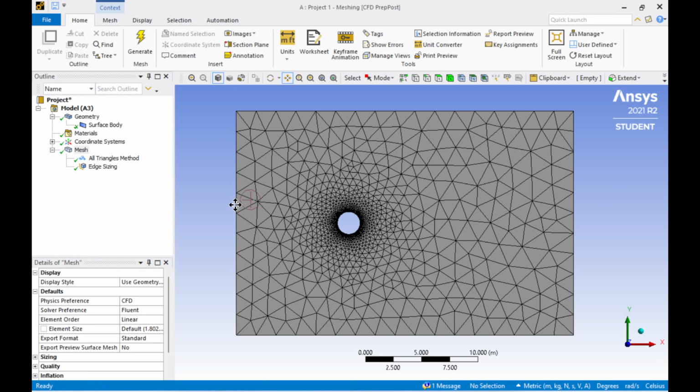This one is an inlet for which we're going to specify velocity. That one is an outlet. We don't want anything to come back to the domain from the outlet, so it can't be a wall. We can't specify the velocity. So there are tricks that we use to deal with this outlet boundary such that nothing comes back.